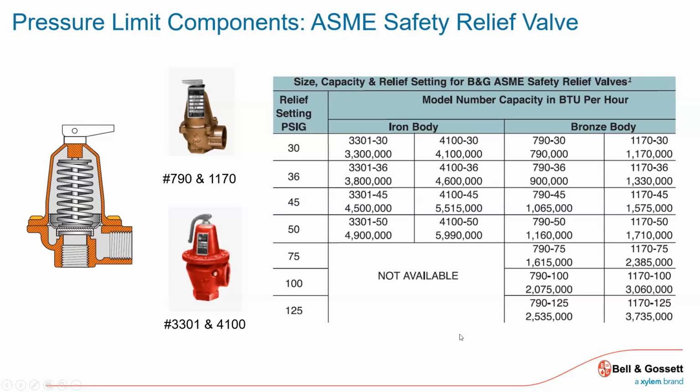There are two settings you want to contend with, especially on the boiler side. One is, what does the manufacturer say is my maximum pressure? I don't want to see pressure above X. This is all I've been tested for. This is all I'm rated for.